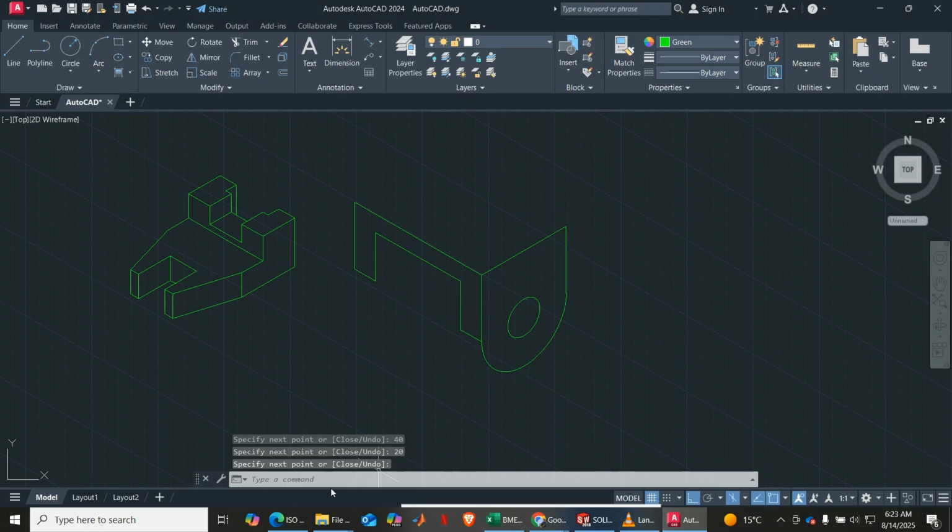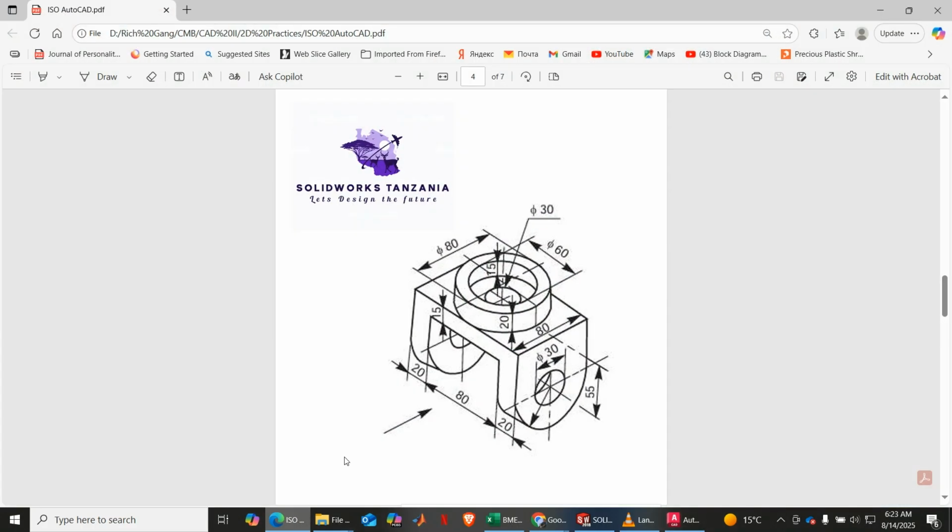Like that. Okay. So how do you go about putting this circle here and this one and that one? How do we go about it? We know the thickness, this thickness here is 20 and this thickness here is 20. So to position this one and that one, we draw a line going in from this center, going in by this thickness, which is 20.